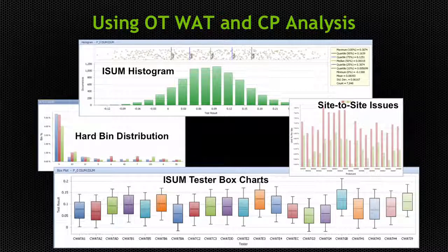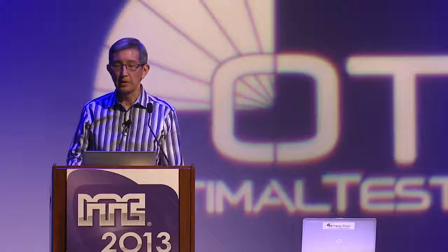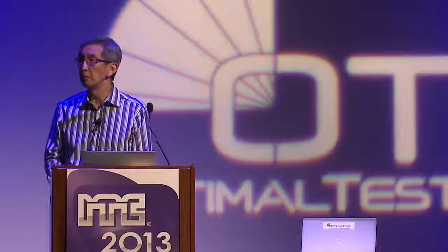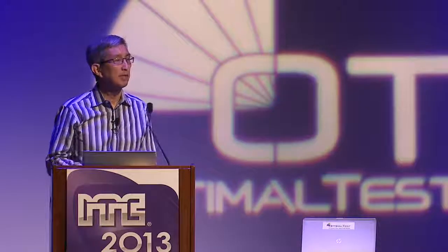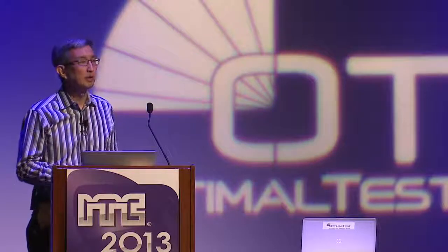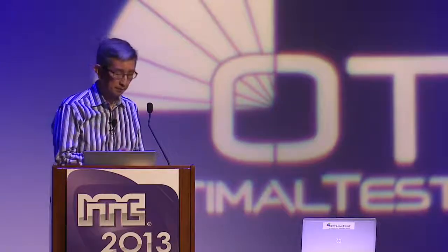We were closely monitoring our WAT parameters and checking how they affect the different yields or the different bins, failing bins and good bins. So we now get this information in minutes rather than hours or days. And our success rate in containing and fixing the problem has become significantly better. Before OT, we wouldn't discover problems like probe card sensitivity until well after the wafer had already been sent to assembly, already diced up and put into packages. And at that point, it's too late. You've already lost those die, and you've already lost the dollars associated with it.